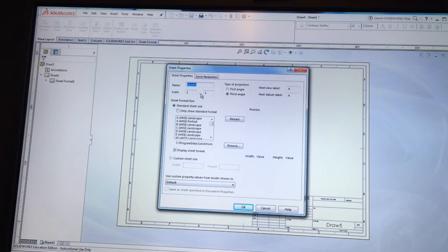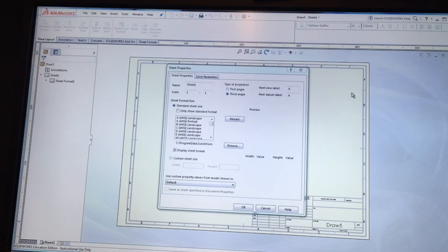So first thing here is you've got your scale 1 to 1. It's also in the bottom of the screen. All right, you'll see it there, 1 to 1. When you have a drawing view added in, you can actually change the scale of the sheet by clicking on that on the page. For our pulley drawings, it's going to vary page to page because some of our parts are really small. You wouldn't have them 1 to 1 because they'd be so tiny. All right, so parts like the washer and the bush, you might make them 5 to 1 instead. All right, we'll get into that side of things when we get to those parts a bit later.